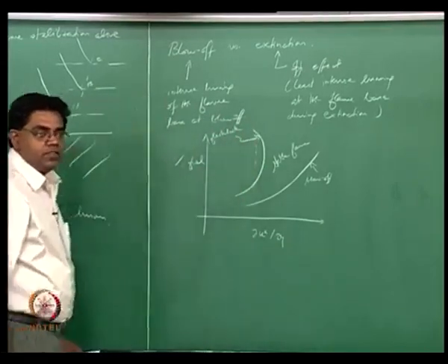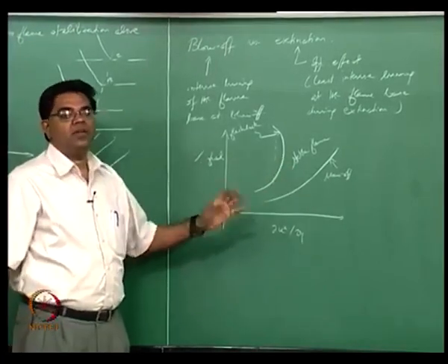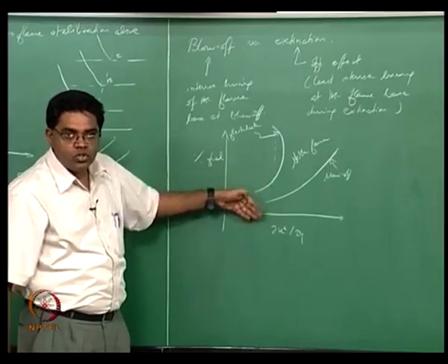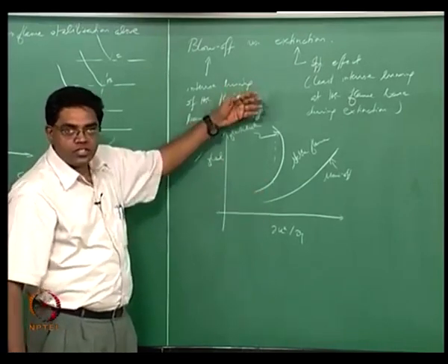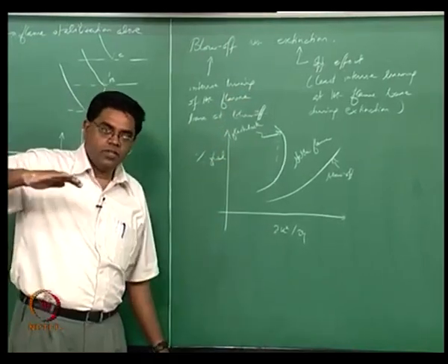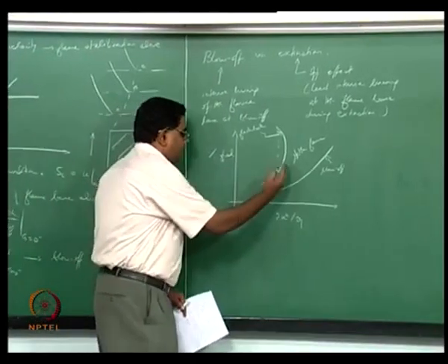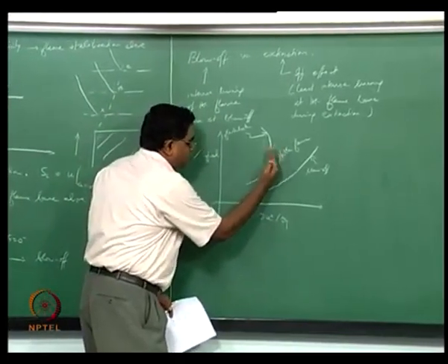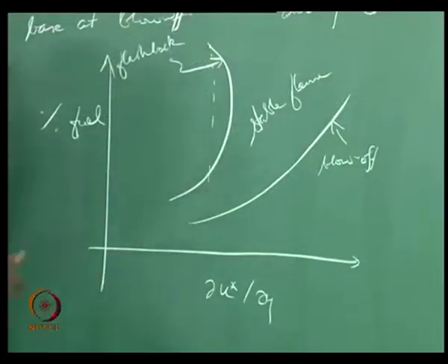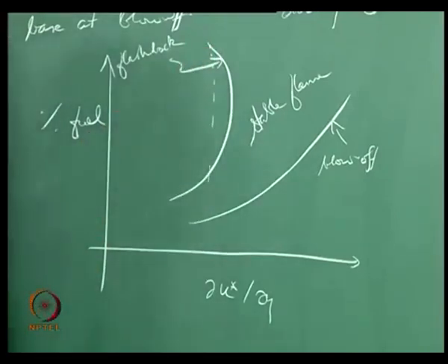That simply means that you could restabilize the flame from a flashback situation either by going towards this region or that region. Flashback is all about having a higher flame speed when compared to the flow. So if you now are below a certain velocity gradient for the flow, then if you are now within the stoichiometric range, you are going to have a higher flame speed.